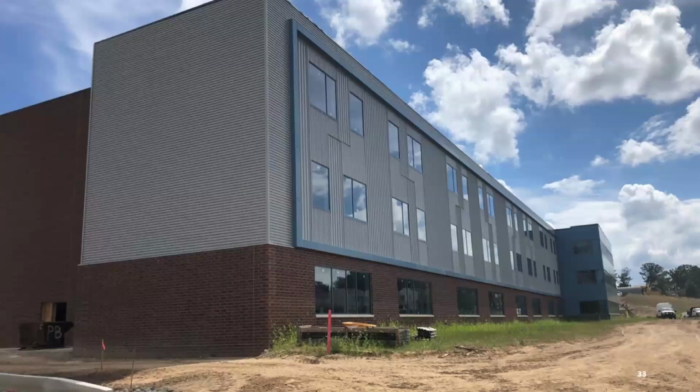Now here's the building after it was completely finished. So all sides of the building were completely weather tight by the insulated metal panel. We have the brick facade on the exterior, incorporated with several different types of single skin profiles and colors. You can see the wall cladding there in the silver areas, but different profiles, the eyebrow details, and then on the far right, MCM panels that were also incorporated.